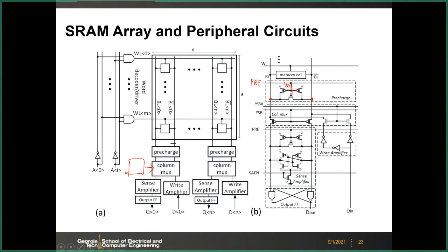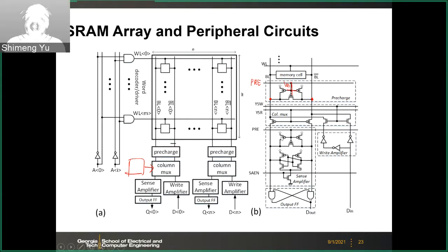And then for the sense amplifier here, again, we have this pre-charge equalizer circuit. This is again to balance those 2 voltages, because for the read operation, we need to have both bitline and bitline bar at VDD. So you want to ensure that this is also VDD to start with. And then the core of the sense amplifier is shown here. This is the so-called latch-based sense amplifier. Essentially here you see a cross-coupled inverter.